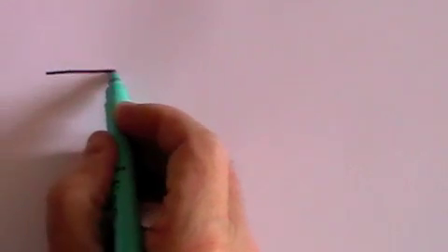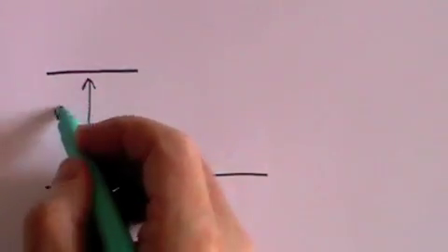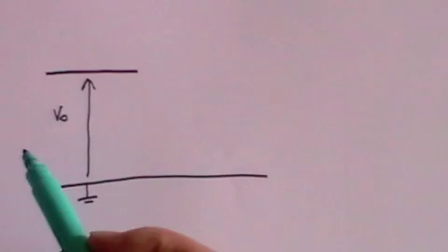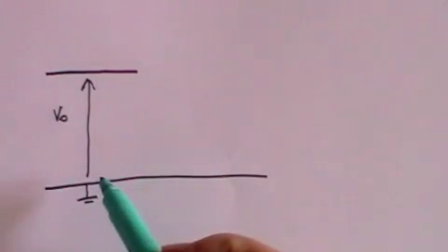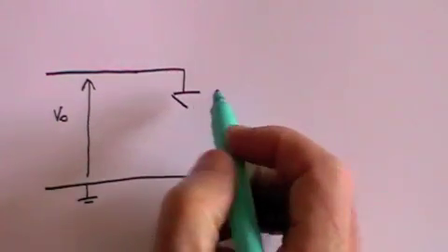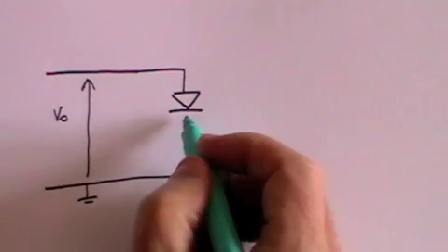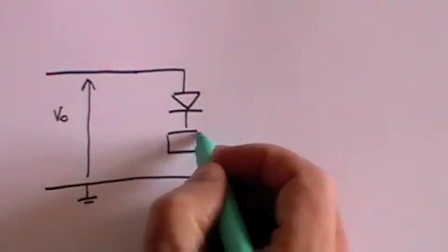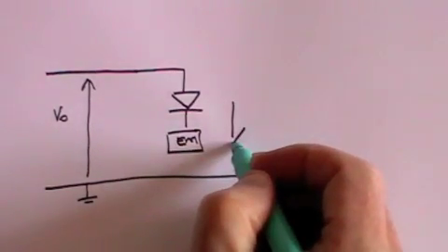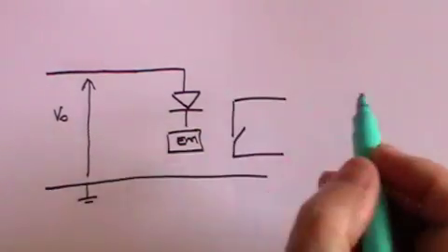And here's a simple way of doing that. Here is the operational amplifier output. Here is the earth line, and therefore the voltage out. From all the diagrams we've drawn in the past, they are all on this side of the line. This is now the output voltage, and what we're now going to do is to connect this to a diode and then to our electromagnet, and on this side we're going to have the switch, which is part of an entirely different circuit.